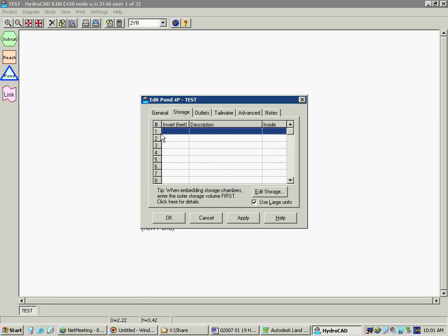Storage, you go into this, and, hey, can I make a comment on that pond catch basin? Sure. Well, we just had a project where we're doing in-ground storage, and this program works well for that because you can set the outlet for that catch basin up as your culvert, and it'll calculate the storage that's available in that pipe, just like in a detention pond. Okay. There are a lot of things you can do in here. We haven't had anything else to design our conveyance systems with for the last 2-3 years, and we've been using this program to do that.